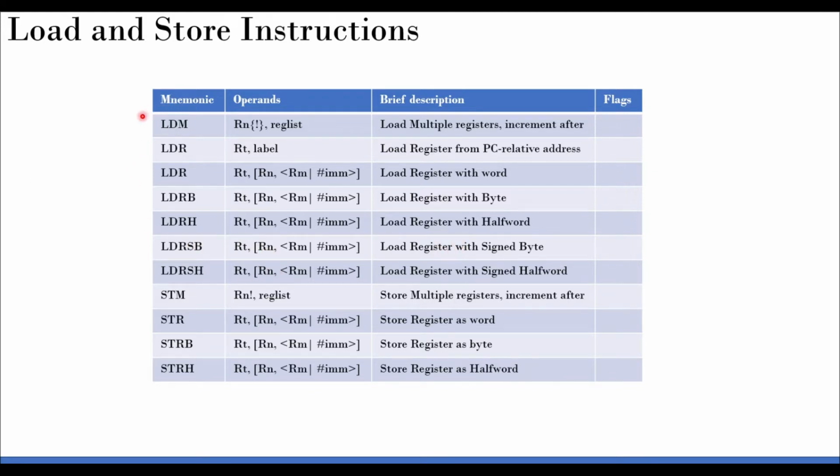And then we do have the option to load into multiple registers. You can give multiple registers here, R0 to R7, and if we have a label here, the full register bank will be filled. So instead of one register at a time, I can fill multiple registers at a time.